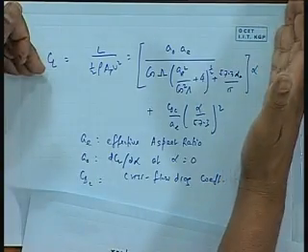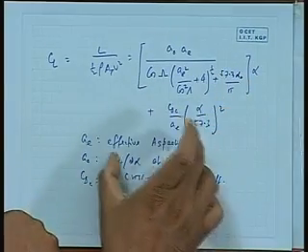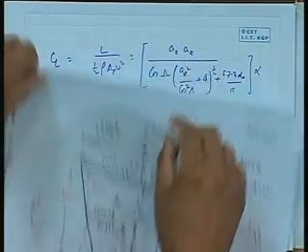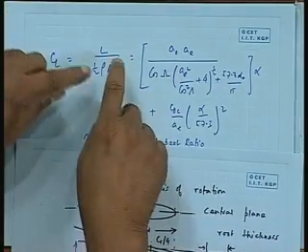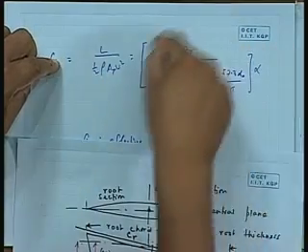You know the velocity of turn, fine. So, I can find out lift and drag. Now, I could find out for a section. Now, I have this kind of complicated section. So, somebody has suggested a formula that you can use. Why this formula? Because it takes care of the aspect ratio, and it takes care of the sweep angle. So, in other words, it is an empirical formula for getting lift in terms of those parameters.